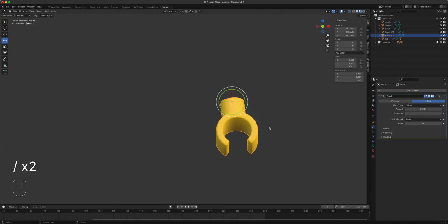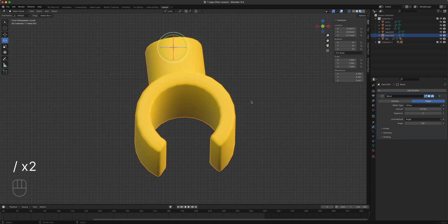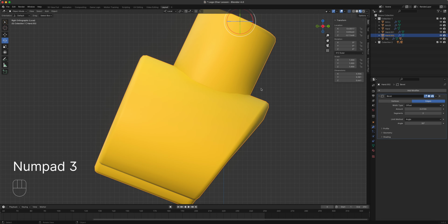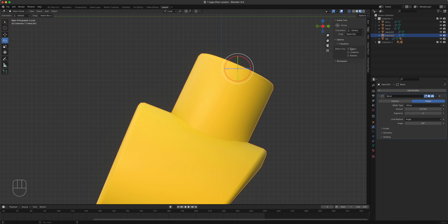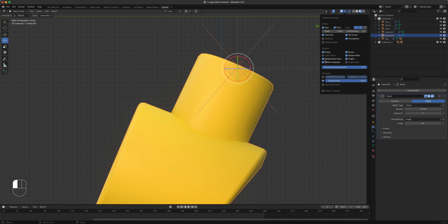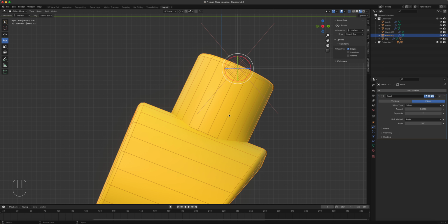Okay, let's isolate this for sure by itself, and then now we're going to go to this side right here, and we're going to have to go to tool, affect the origin only, and it's already kind of at an angle, and we just want to make sure that we're going to follow kind of like the straight. Okay, I'm going to turn on wireframe right here so we could see the lines right here, so we could match that angle easily.